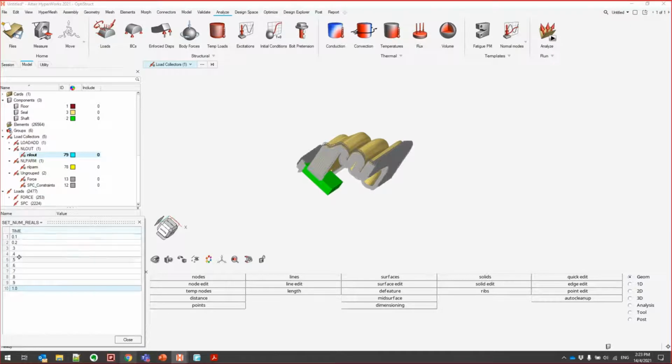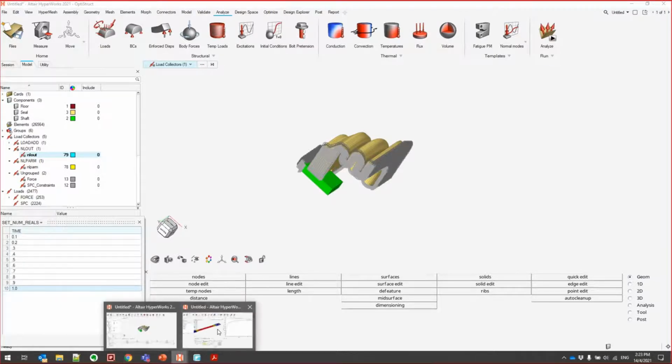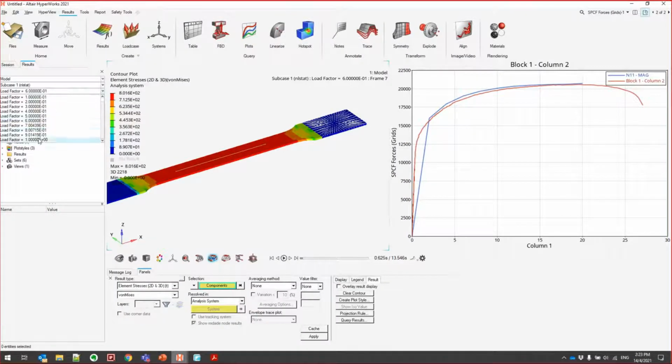So if you define it this way, you force the simulation to be carried out at this particular time, and then output at this particular time or load increment. If you don't do this, then you see previously in our examples, you see that our time step may not properly capture exactly at each 0.1 interval. Okay, you see there's a variation there.